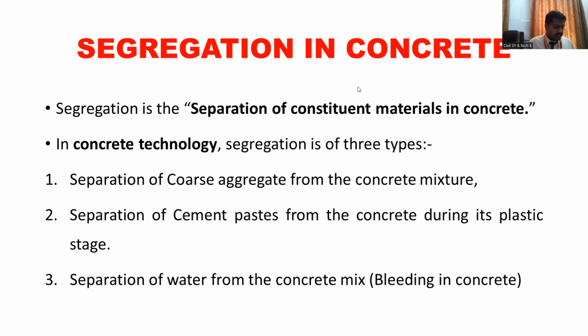Okay. आता segregation होतं कधी? सगळ्यात महत्त्वाची गोष्ट. Why does the concrete get segregated? If you do over compaction, definitely you are going to face the problem of segregation.